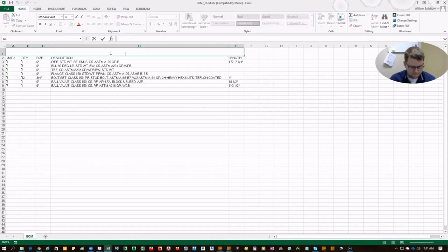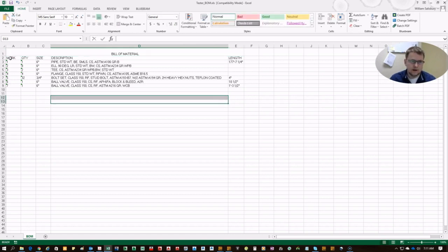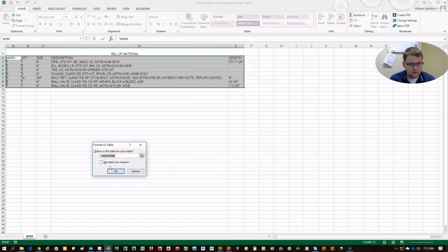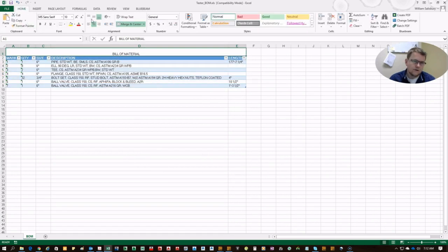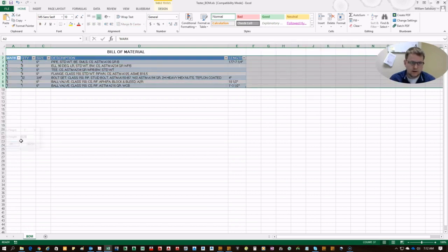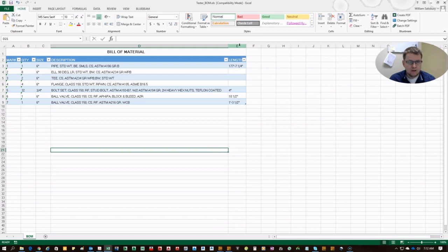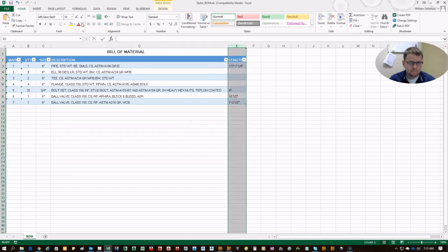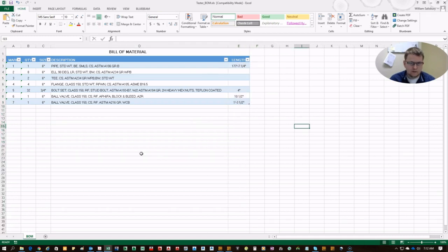So, you can apply this as a table and just clean it up a little bit. Set the headers, center them, make them a couple sizes bigger or bold. Height 15 and 20. Space to spare. Setting the functions. And that's basically it. So that'll start looking like a regular bill of material.